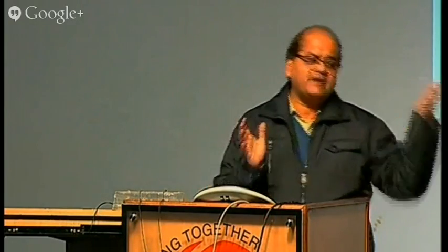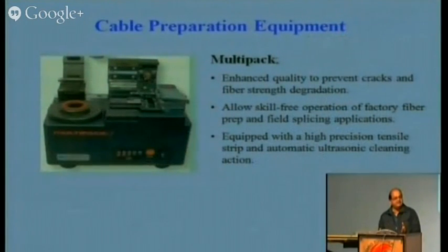This can be also manual or some equipment is also available. We call these the polishers. So mostly they are the multi-pack polishers. For a single fiber, you can go for this process, but when you have a multi-fiber cable, 24, 48, 96, it will take a long time. So in that case, these polishers are very helpful. All the fiber bundles you can put there, and it will polish all the fibers in a single instant. So polishers can also be used for these applications.